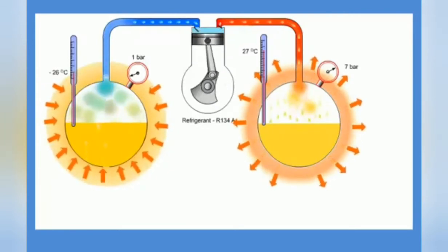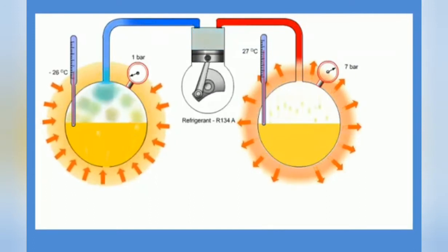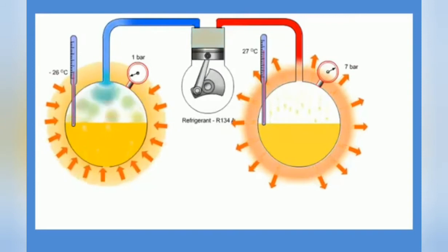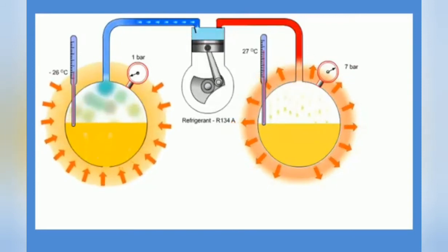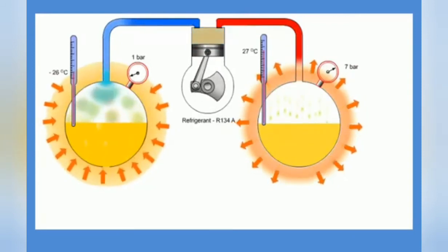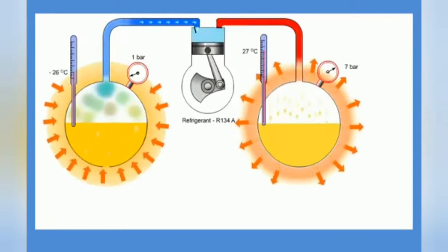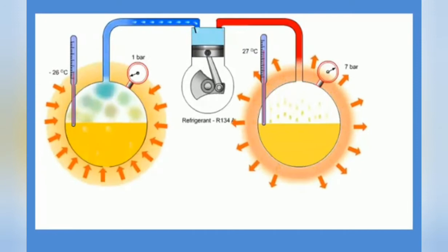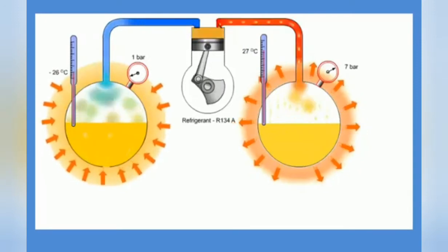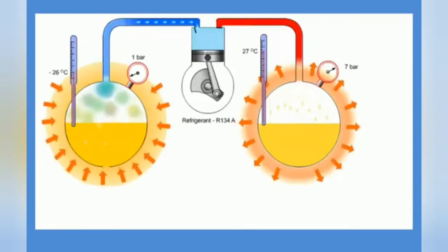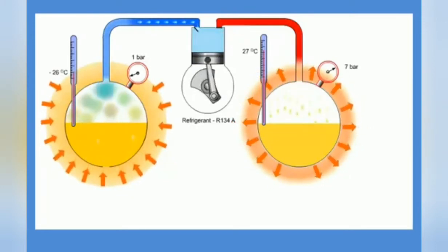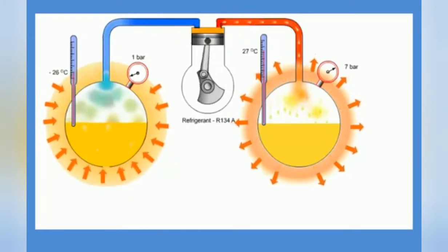As long as vapor refrigerant is supplied to the flask, the condensation continues, causing a heat transfer flow from the flask to the surroundings. This process is exactly the opposite of what is going on in the flask on the left side of the picture. The flask on the right side of the sketch is representing the third main component in a refrigeration system and is called a condenser.